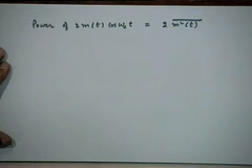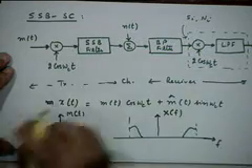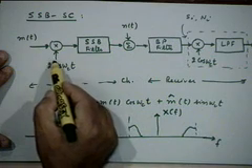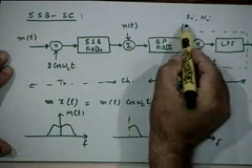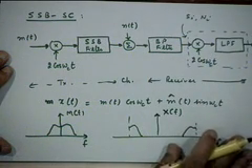That's straightforward. When you remove one of the sidebands, how much power you are left with? Half of this. So therefore, what is the input signal power that is coming in here? Once again m square bar, and that is the reason why I am multiplying with 2 here. Basically the idea is to normalize S sub I in every case to equal to m square bar if it is possible, right, just for the sake of convenience.